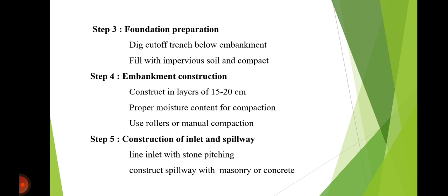So next is the construction of the embankment, which places the excavated soil in layers of 15 to 20 centimeters, with proper moisture content for compaction. Use rollers or manual compaction.